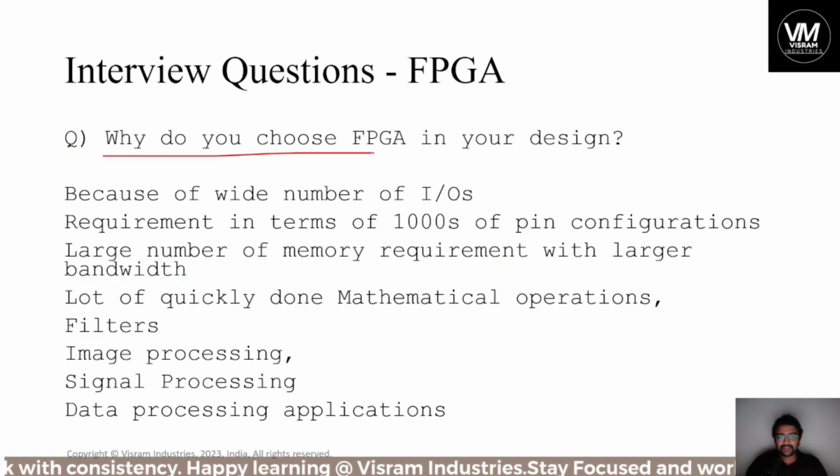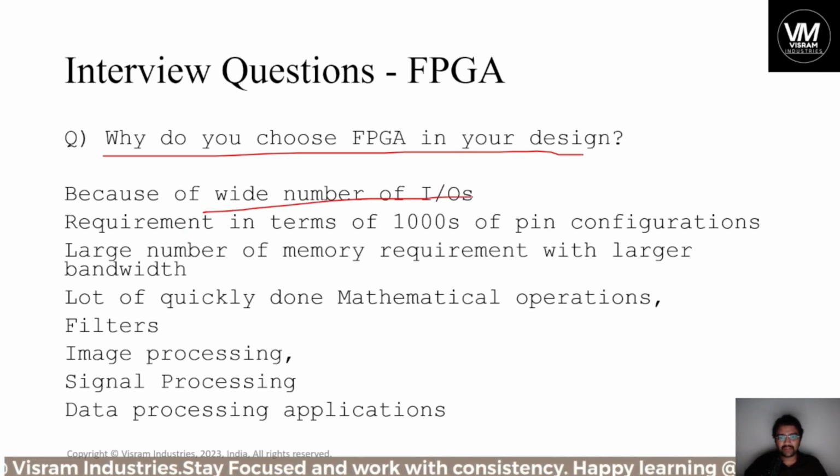Next question: why do you choose FPGA in your design? There are several reasons for choosing FPGA instead of microcontrollers. If you have a larger, complicated design that requires a wide number of IOs to be connected with different peripherals like buttons, keys, LCD, USB port, Ethernet port, HDMI cable, audio signal conversions, audio jacks, and other pin configurations like GPIO pins, these kinds of IOs are available on the FPGA motherboard, and that is one reason.